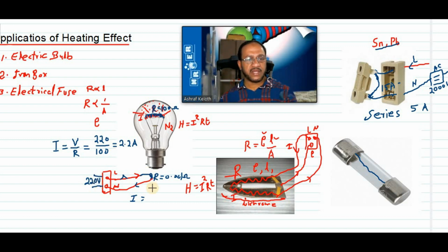If these two are coming in direct contact, the potential difference is 220 volt itself, and the resistance here is only 0.001 ohm. Then what will be the current? There are 3 decimal positions here, 1, 2, 3, so I should add 3 zeros in the above, isn't it? 2,20,000 ampere is the current. When you touch these 2 points together, the current flowing is 2,20,000 ampere.